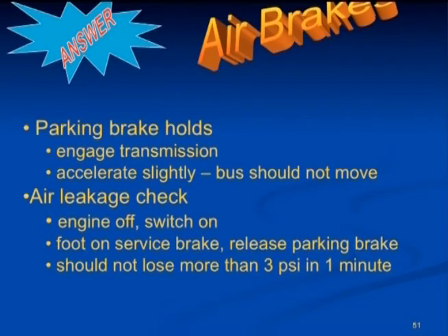Make sure that your parking brake holds. Engage the transmission. Accelerate slightly. The bus should not move. And check your air leakage rate. Turn the engine off, put the switch back in the on position. With your foot on the service brake, release the parking brake, and you should not lose more than 3 psi in 1 minute.